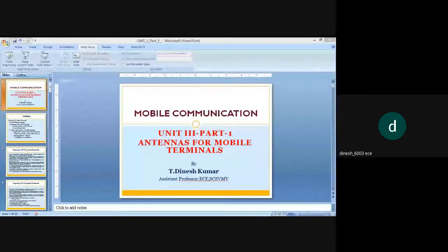For this, repetition coding can be used over a long block to achieve reliable communication, but the corresponding data rate goes to zero with increasing block length. So repetition coding does not pack the code words in the available degrees of freedom in an efficient manner.